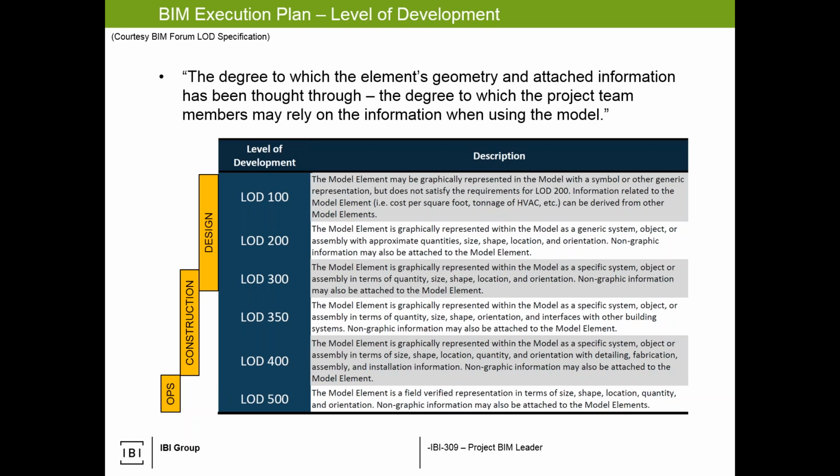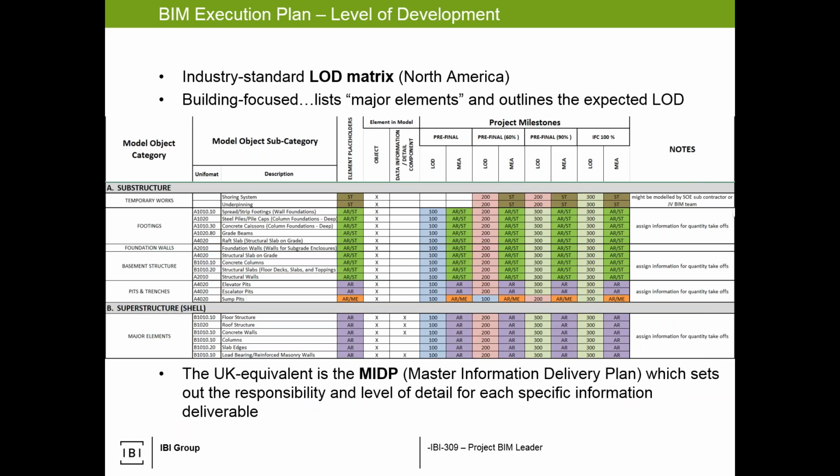So just be cognizant of that. I've been on several discussions where they say, oh, just do a little more. Sign the dotted line for 350. Some RFPs have said do an LOD 500 model, and that's just one big red flag right there from a designer's perspective. So be cognizant of level of development.